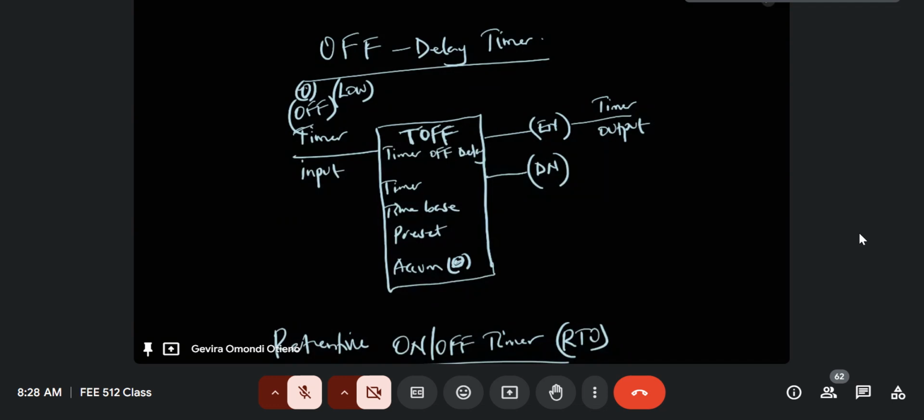And that also happens with the on delay timer: for cases where there is a power loss, or we have an off instruction or a 0 logic provided at the input of the timer for whatever reason, the accumulated amount will be lost.